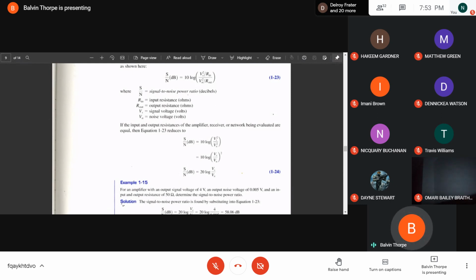But there are two things that I suggested you need to take into consideration, because they will guide you a lot. One is your actual budget from a cost perspective, and two, your link budget, in terms of the power budget. I might be transmitting this signal, but I might need an amplifier that transmits at this level, as compared to a small amplifier that transmits at that level.